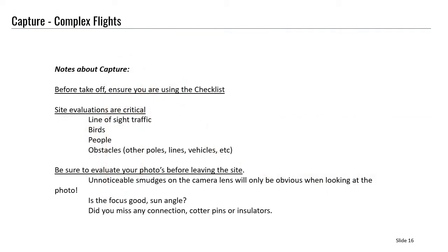Now, before leaving the site, run down your checklist. There are just a few items that you need to be aware of before takeoff and before leaving the site. Here are a few notes that you want to be sure are done. Before you leave the site, make sure that when you're looking at the photo, the focus is good, the sun angle is correct, and you want to think to yourself, did you miss any connection, any cotter pins, or any insulators?